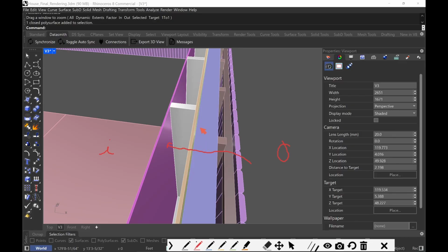And some people say as long as you're providing ample insulation, ample exterior insulation, depending on the climatic region, then you don't have to worry about the interior insulation, and you can keep your drainage plane and your vapor permeability with this drainage plane here, okay?